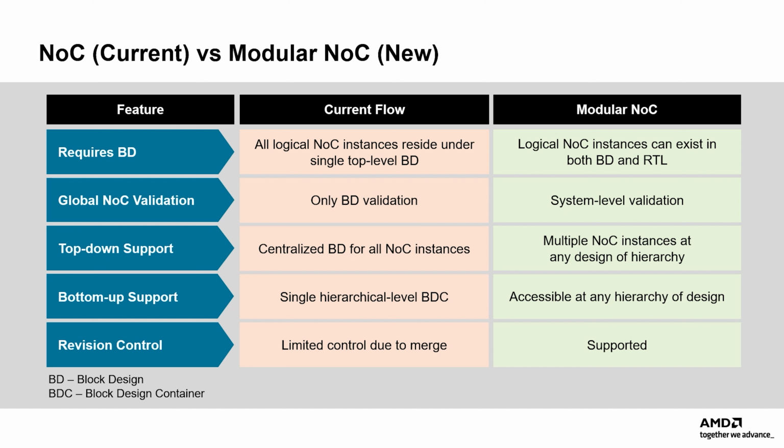Similarly, for the top-down and bottom-up design approaches, the modular NOC flow becomes more flexible when using RTL. With RTL, users can instantiate multiple NOCs which are easily accessible within the design hierarchy. Revision control is much easier due to the flow being primarily an RTL solution and not having to manage changes to block designs for additional NOC usage.